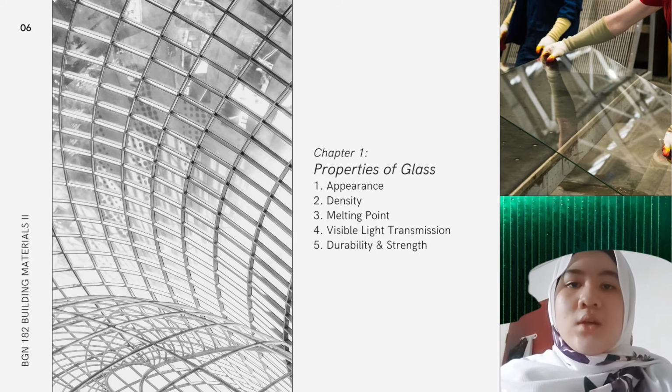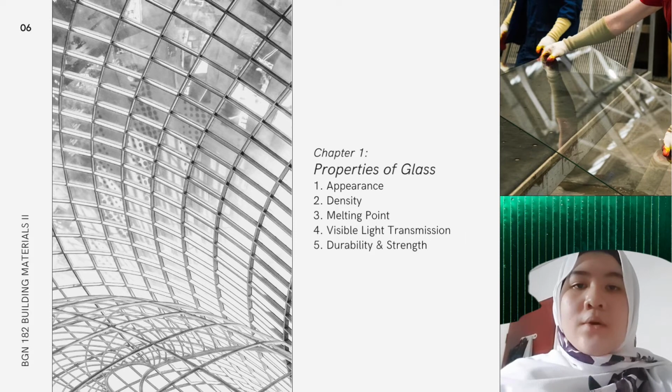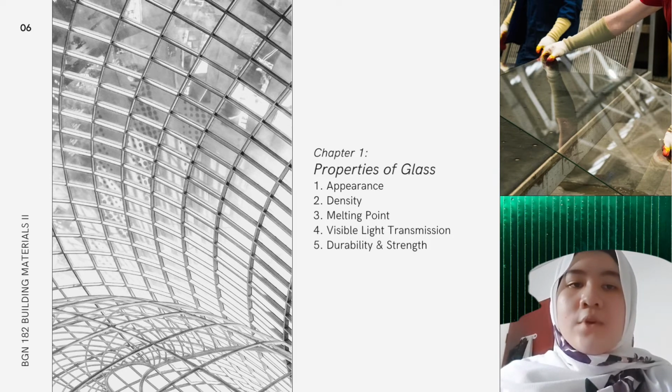Defects to the glass: all the glasses are subject to deterioration by the action of water, which means it should not be allowed to remain wet. It may also be damaged by the permanent oxidation in the unventilated cavities between the sheets of the glasses, which means it should not be allowed to stack face to face. It can be attacked by hydrofluoric and phosphoric acid and by the strong alkalis, which means damage effects are very difficult to remove except by polishing the surface.